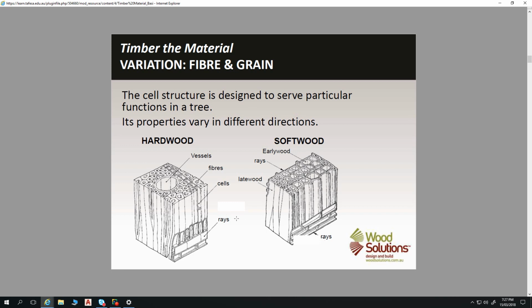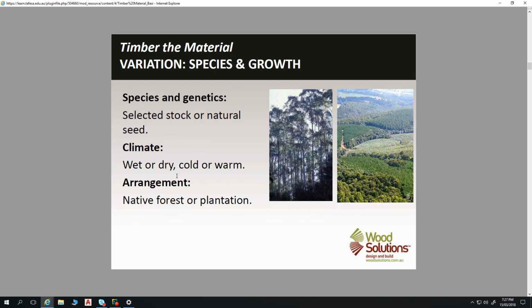as hardwoods and softwoods not so much by their characteristics, but by the way in which they grow. So softwoods have regular cells, whereas hardwoods have these vessels within that have cells packed around. So these intermediate vessels in them, and that's the difference between the structure of the two, and that's the difference between the classification as well between hardwood and softwood.